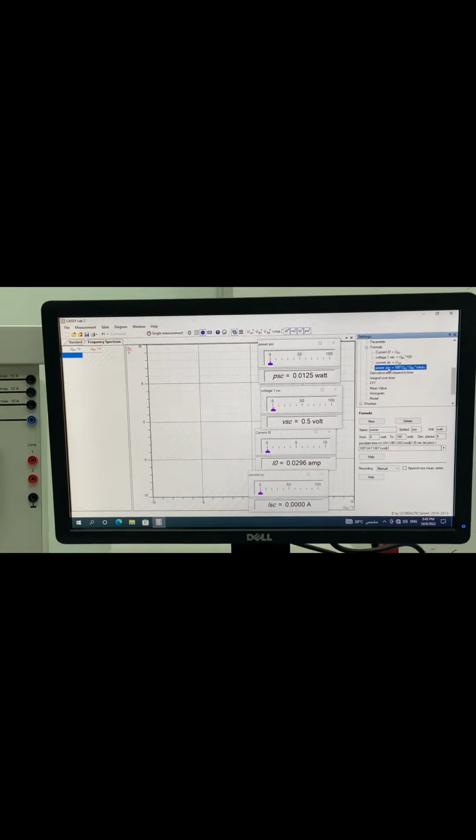1.36, right? So you have to be careful that the voltage we apply in the primary, so that the secondary current does not exceed this value. Because this is the maximum value the transformer can handle. So now we turn on, like we have defined everything.